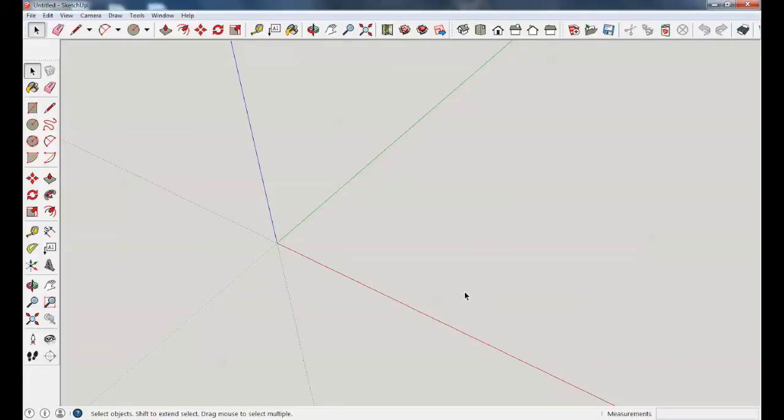For our first step we want to select the Shapes tool, which can be seen here. Mine is already pre-selected with the circle, but if yours isn't you need to select the little arrow on the right of the drop down menu and select Circle. Now you can drag the circle to the center of the three axes points and it should snap to the middle and say Origin. There we are. So it snapped, says Origin, and the center point of the circle has turned yellow.